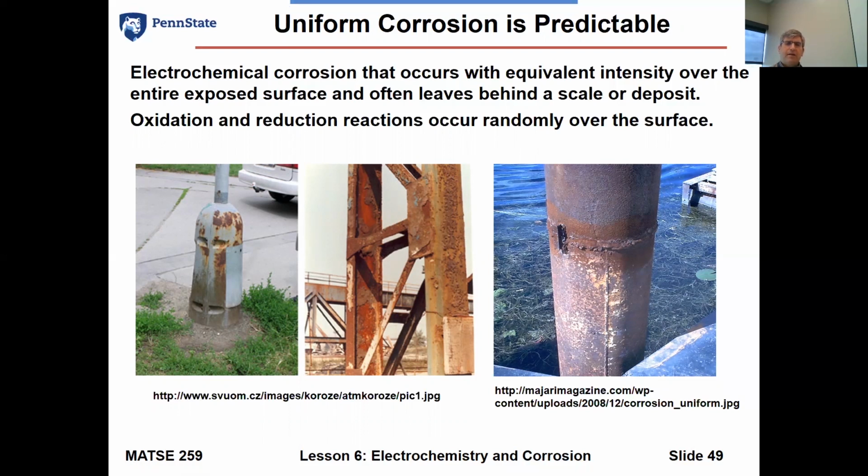And with that, we can sort of watch how corrosion occurs on these. Say for this bridge section, there's a lot of corrosion on it, but what we can do over time is just measure the thickness and measure that loss rate, the corrosion penetration rate that we talked about, where we have a certain loss in mils per year, hopefully.